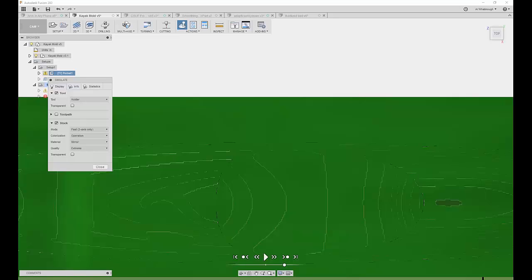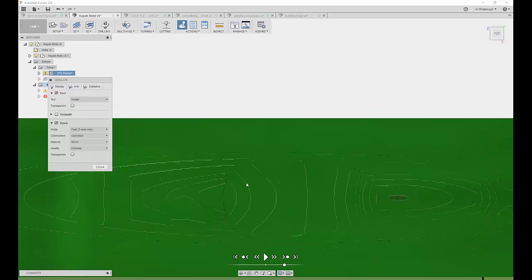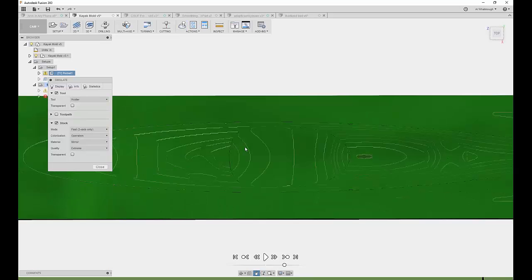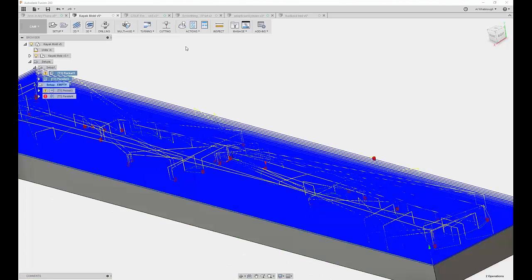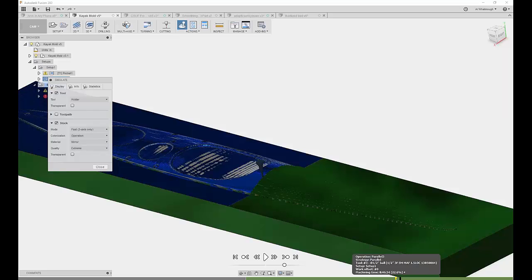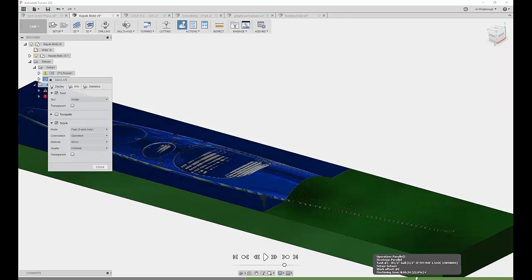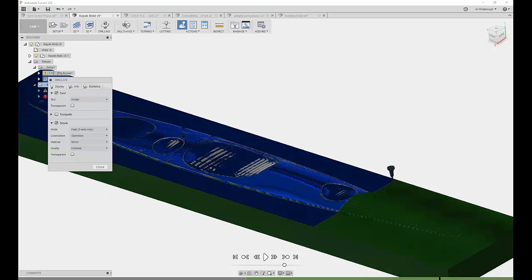That's happening in the standard mode. In the 3D mode, it doesn't have to do a full recalculation. But of course, if you move it very far back, then it's sometimes faster to simulate forwards again. But the standard mode can only calculate progressively. In particular, because it has to do the collision checking, it cannot reverse the stock simulation. So that's one of the benefits of the 3D mode, where the standard mode requires you to recalculate everything from the start.